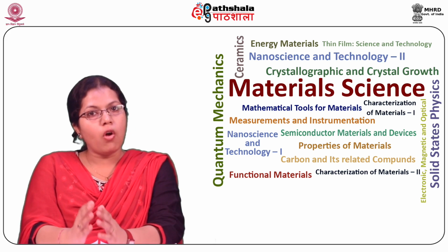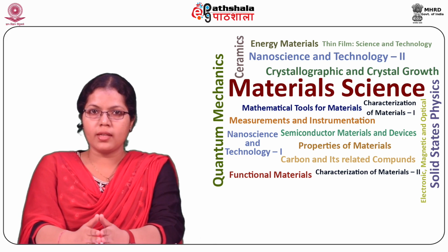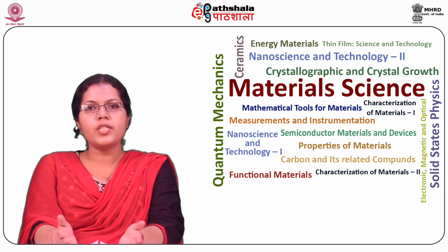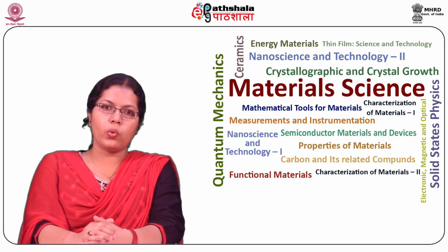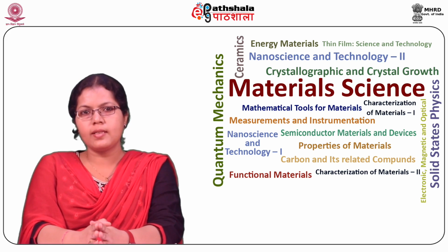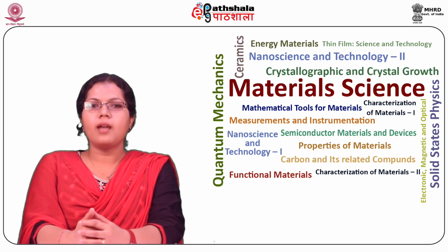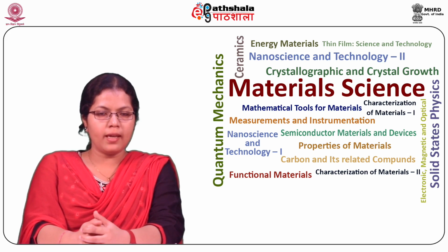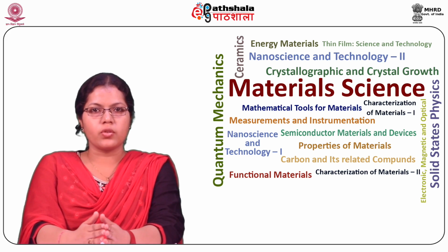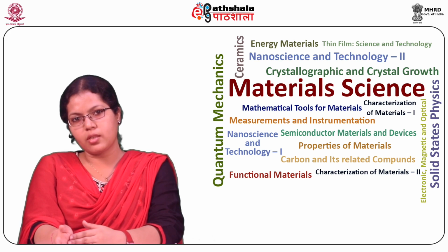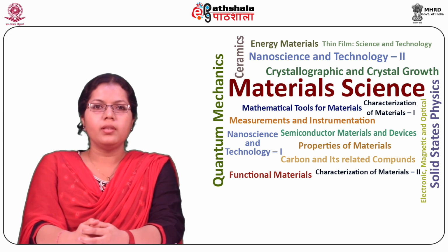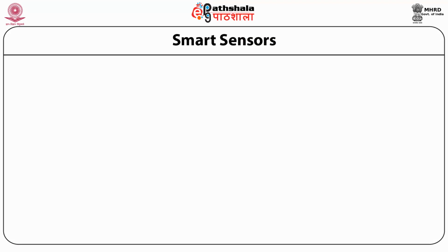The smart sensors also possess a built-in digital interface that provides a communication channel with the network control. A functional smart sensor system consists of two main components, namely the Transmitter Interface Module (TIM), which contains physical transducers and data acquisition system, and the Network Capable Application Processor (NCAP), where control and data correction take place. Now let us see what their functions are.